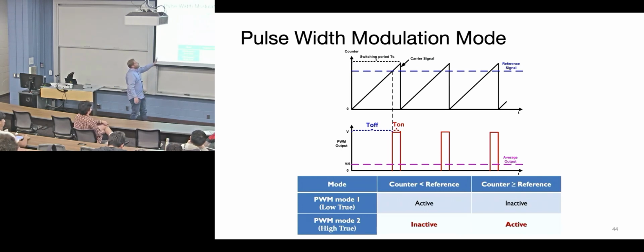You can imagine you could have a counter that's going to count from 0 up to some value, hit that auto reload value, and then go back to 0 and keep counting up. So we get these steps going up. And you could have another piece of hardware that's going to come through and basically say, if you're over this value, that blue line, then we're going to turn our duty cycle on or off.